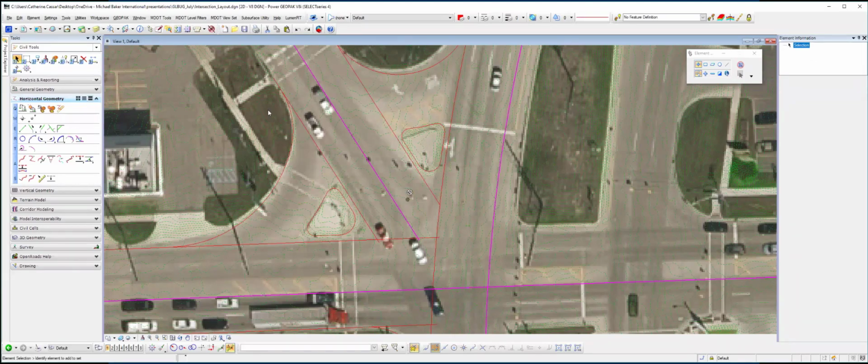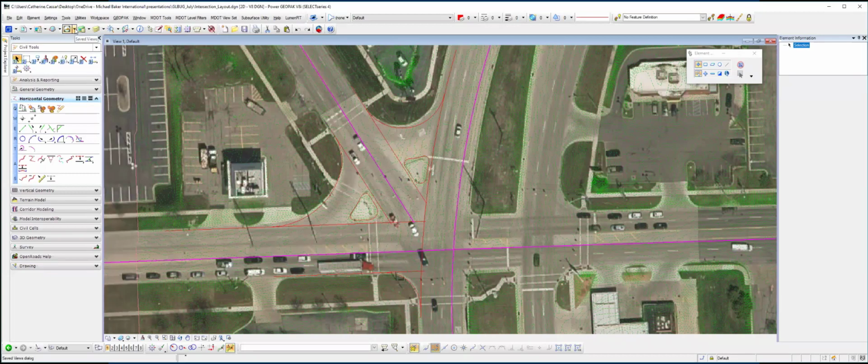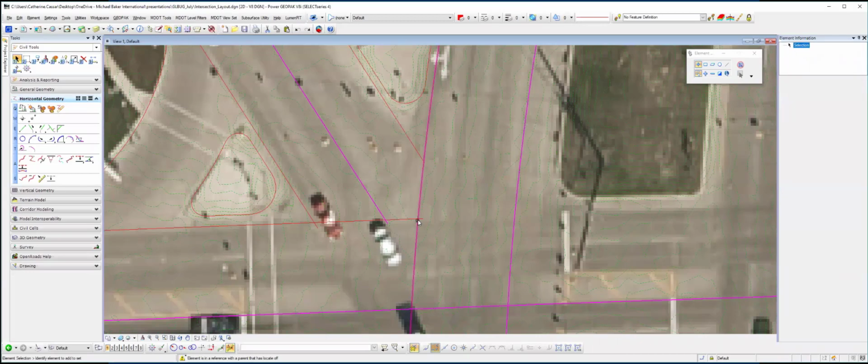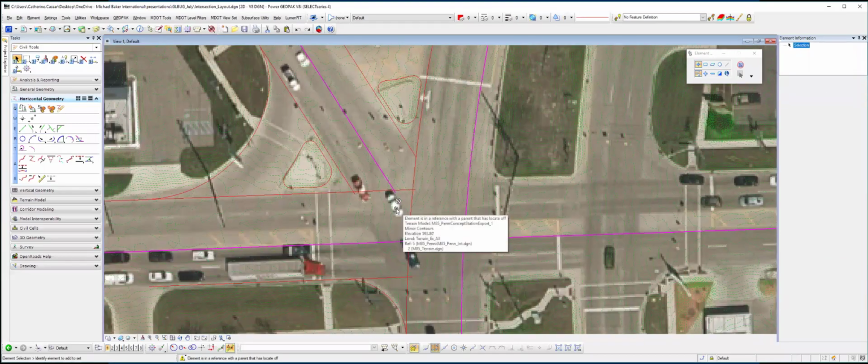So that's generally how that layout would work. All of that doesn't take necessarily too long. And you'll notice my edge lines do cross that main line edge here. I'm coming across it because I want to be able to get the vertical information precisely at that edge, to make sure that all of these baselines actually will connect and I don't have any odd bumps or gaps in my terrain model when I get done.